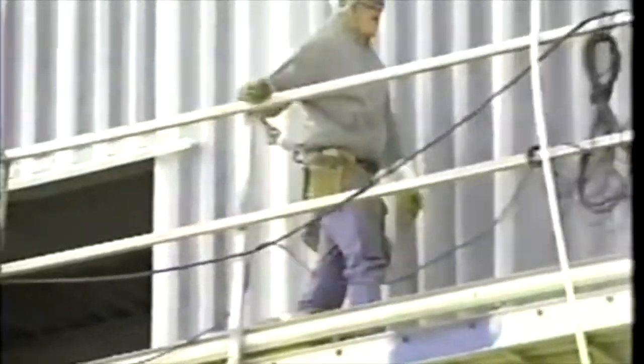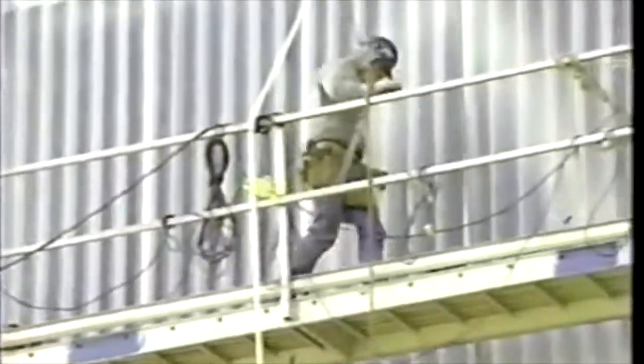The swinging scaffold, or 2-point suspension scaffold, is a platform not less than 20 inches nor more than 36 inches wide overall. It is supported at each end by metal hangers or frames designed to incorporate guardrails, toe boards, and the hoist mechanism.